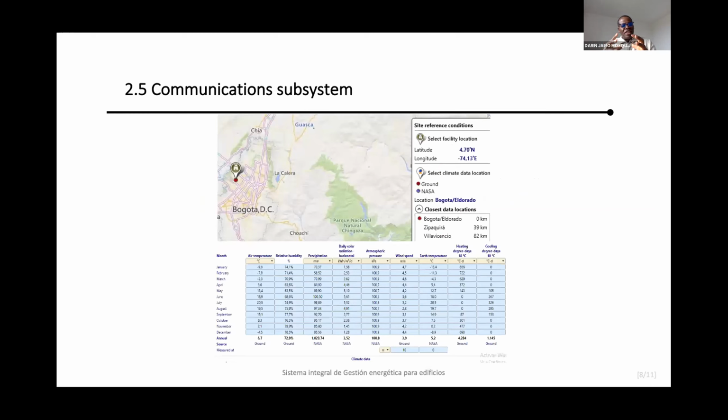The communication system proposed is a support for management of the building. It is structured with two communication channels, PLC system, power line communication, and conventional wireless Wi-Fi. The communication system allows sending and reading between the user and the general management system, allowing the location of the user or the climatic conditions of the places to be obtained.